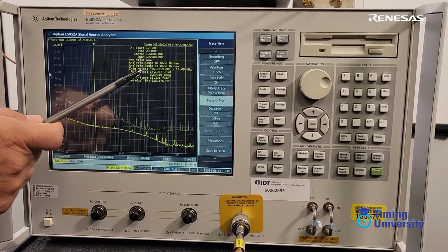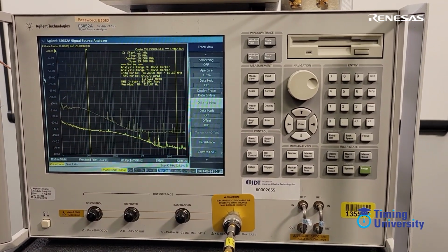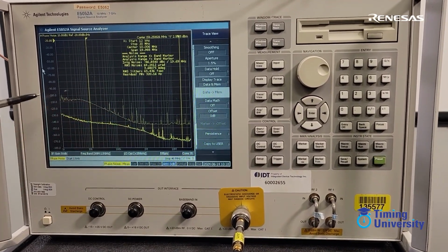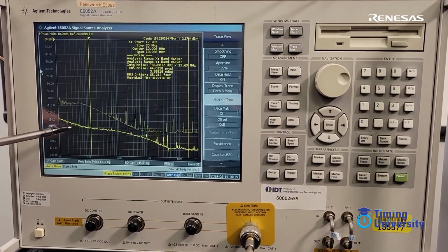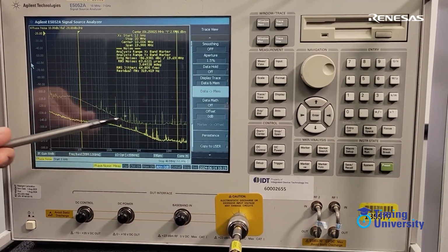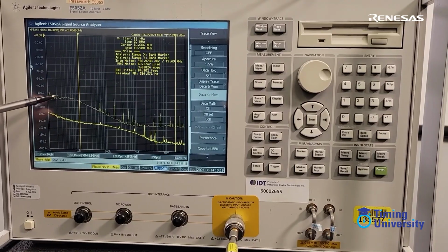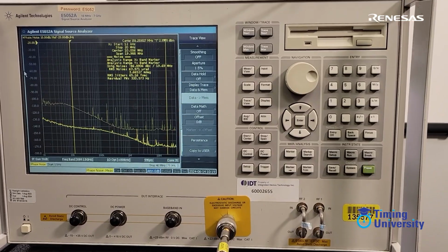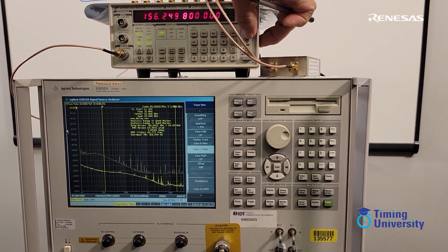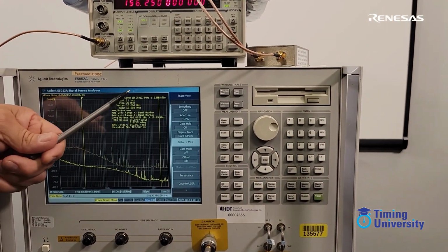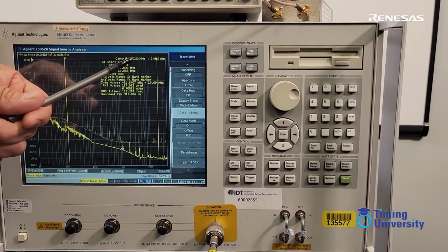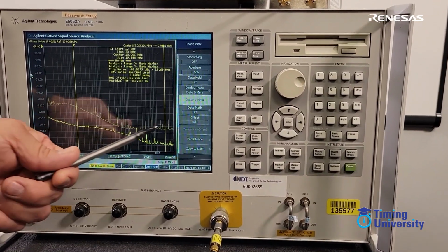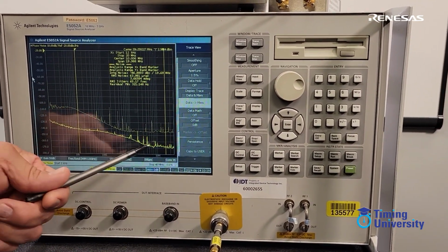So you see this is 65 femtoseconds. The clock source that's coming in is very noisy, but the jitter attenuator is tracking it and providing this very, very clean output. So from more than 900 femtoseconds down to 64, here we go, 64 femtoseconds. Let me adjust the clock just a little, just to show that it is running. We're going to increase the frequency just slightly, and you can see that the frequency has increased. So that's it. This is showing the before and after the output from the jitter attenuator.